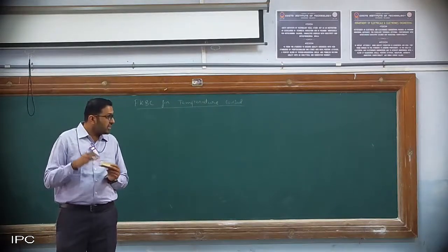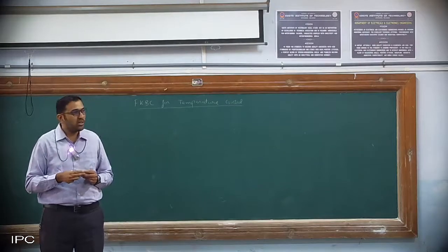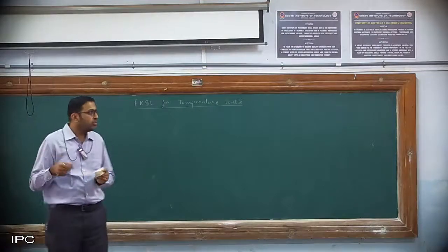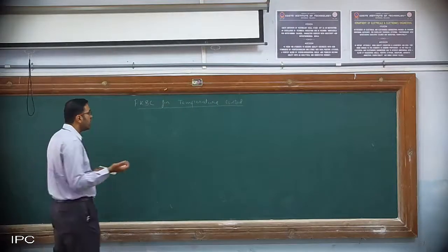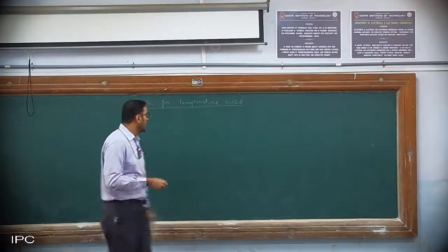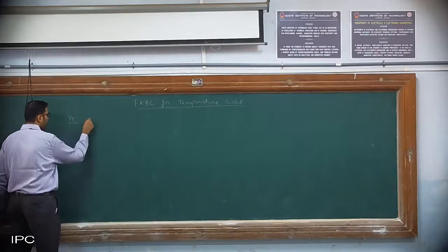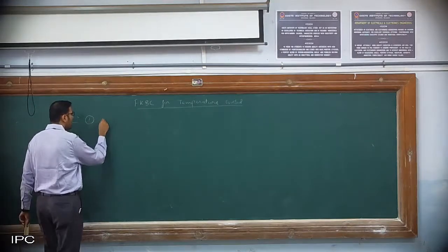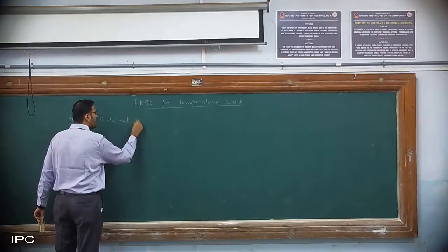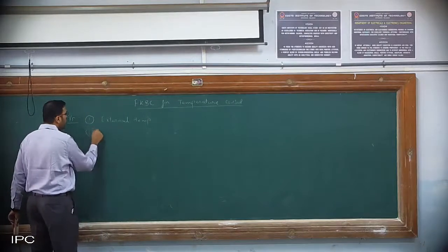Now this temperature control, or the controller for this temperature control, needs to be designed using fuzzy logic. Fine. So in order to do this, again the same thing, we need to select the input and output parameters. Okay. So our input parameters are, first, external temperature. Second, humidity.